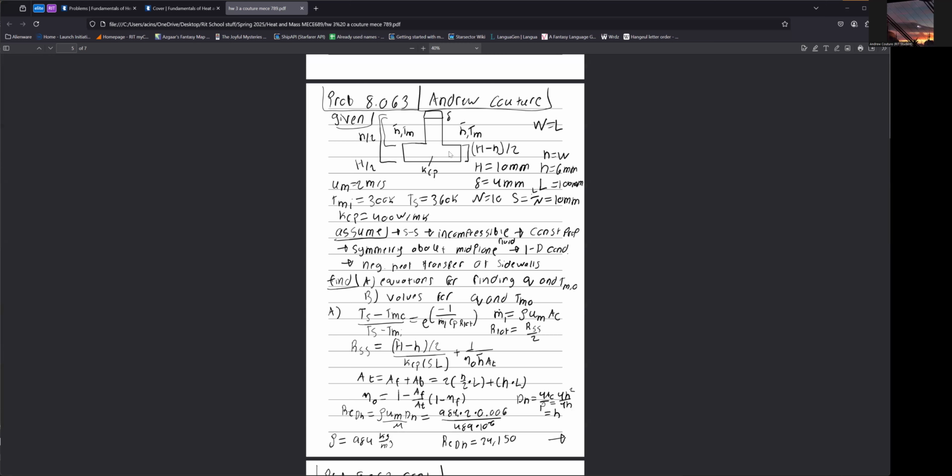There's 1D conduction, which is also tied to the symmetry. You're basically assuming that any heat transfer outside of the midplanes is negligible. So it's 1D heat conduction in just one direction, and negligible heat transfer through the sidewalls. So mostly just up and down heat transfer through the part right here. This would be the sidewall. So it would be up and down heat transfer through stuff like this.